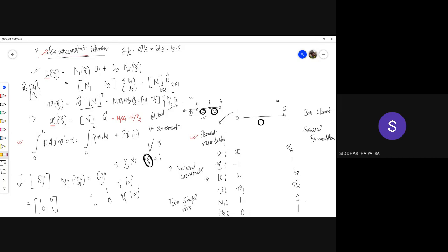Now about the shape functions. You could have chosen any type of functions, exponential, logarithmic, sinusoidal, as shape functions, but the simplest one we can think of are polynomials. Now what polynomial can you construct? Let's say these N1 and N2 are polynomials, and you have the value of N1 at 2 locations and the value of N2 at only 2 locations.